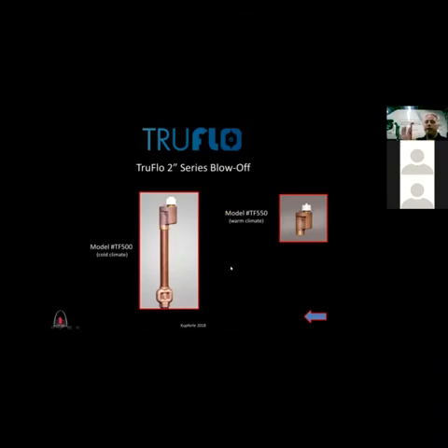And these are designed for those dead ends where you don't need a lot of maintenance. You don't have to flush it every week because I don't have water quality issues. These are for your specs to go on the dead ends. So if I do need to flush a line, I have a good working hydrant blow-off that I can operate from above ground. I can repair from above ground, or I can flush the line when I need to. But it's not really something that's going to work on water quality unless you have a bad dead end. You'd go out and flush this thing manually every week.